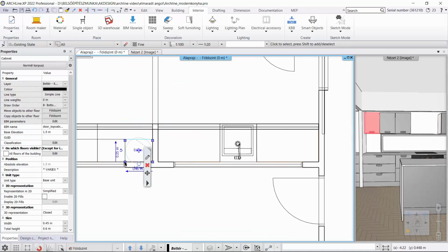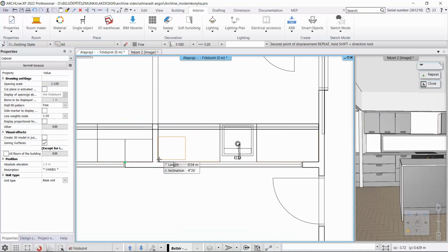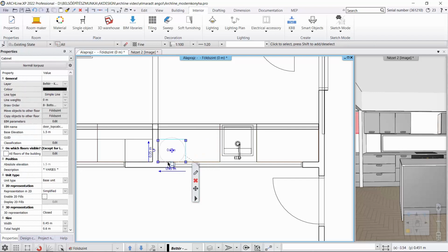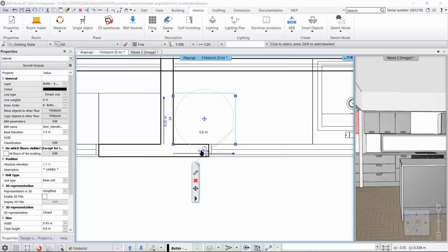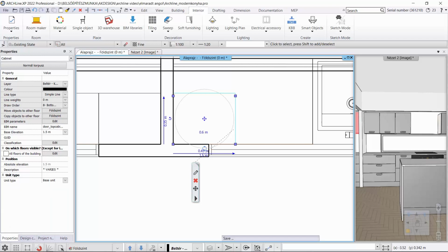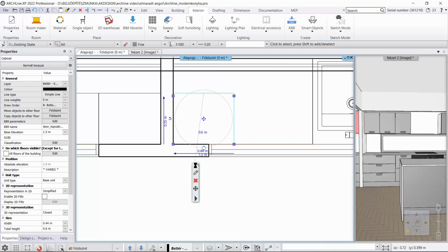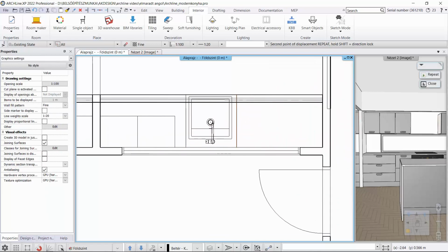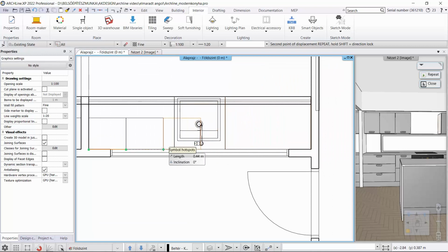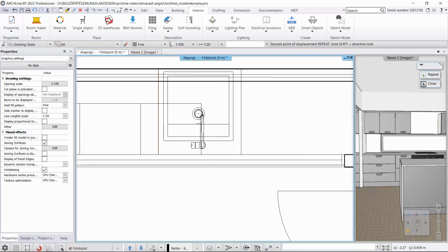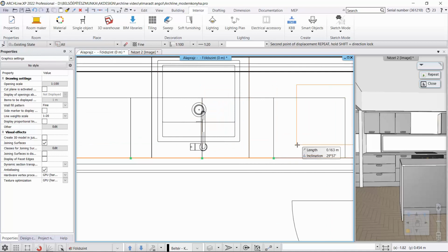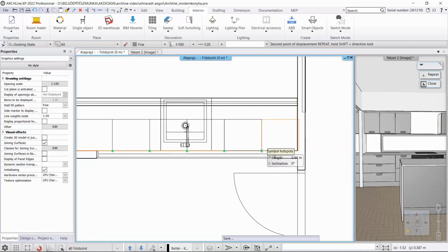Let's continue placing the upper cabinets in the utility room. I copy a cabinet, put it in its place, and then rewrite its width, because only 440 mm elements will fit here. First, we reverse the small arrow and rewrite the width to 440 mm. If this has happened, I will copy this again side by side 5 times. Our last piece will be 402 mm instead of 440 mm, so we will change this as well.